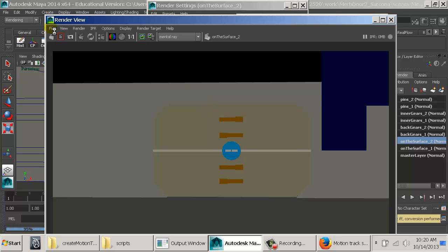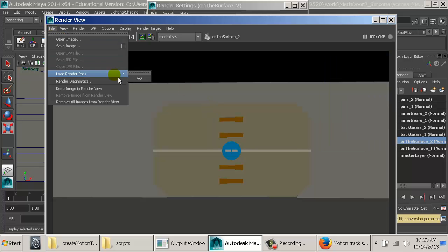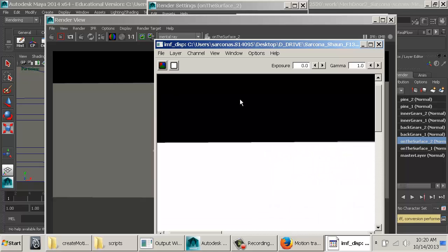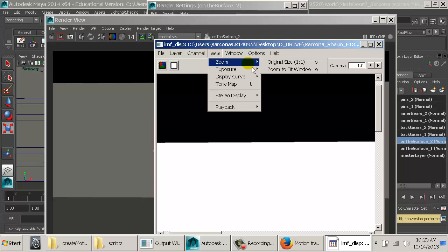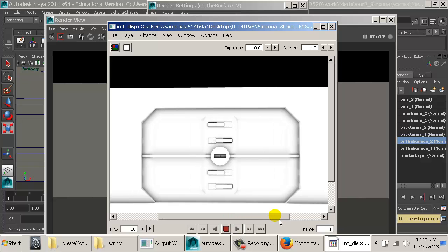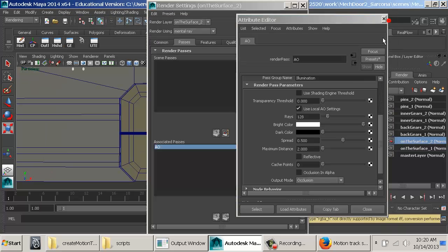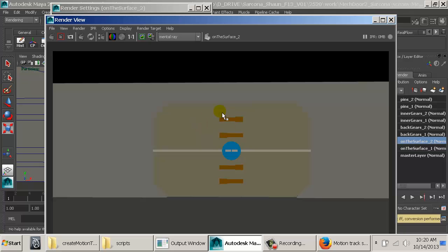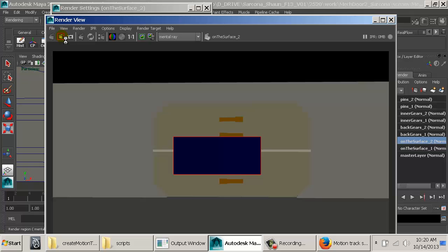Okay, we're just about done. Then we can check our pass. Okay. Actually, I think I introduced maybe a little bit more noise into our scene by lowering the settings. So again, it's a game we play with. Instead of going down, let's take this up. Let's go to 10. And I can always go and render just a section of this. Like if I saw that this is where I was having a lot of trouble, just grab that section and render it.